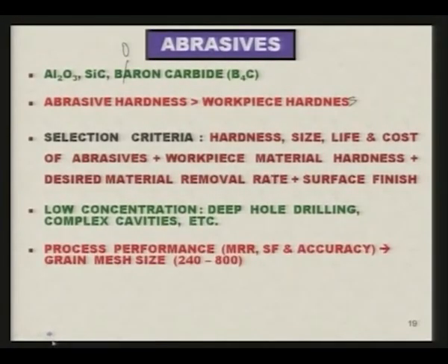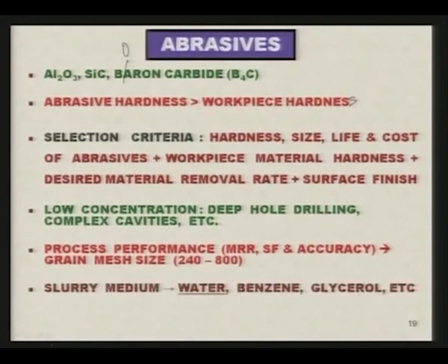Process performance is evaluated in terms of material removal rate, surface finish and accuracy obtained on the machined component, and it is a function of grain mesh size of the abrasive particles. Normally mesh size selected for USM ranges between 240 to 800 mesh size.